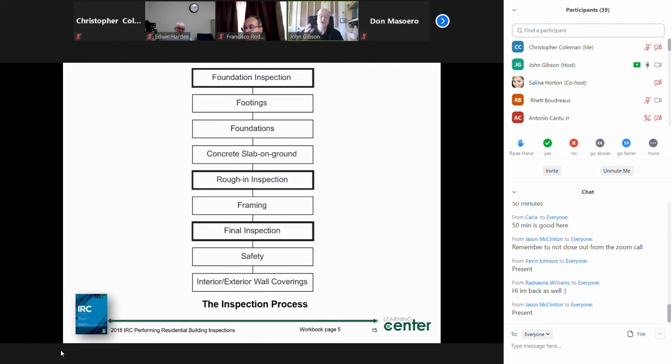And then I'm looking at the stair components to see tread riser geometry. Once you've put the actual stairs in, then I'm looking for handrails, I'm looking for headroom, and all of this may happen sometime prior to getting it finalized and turning it over to the actual tenants or owners to be